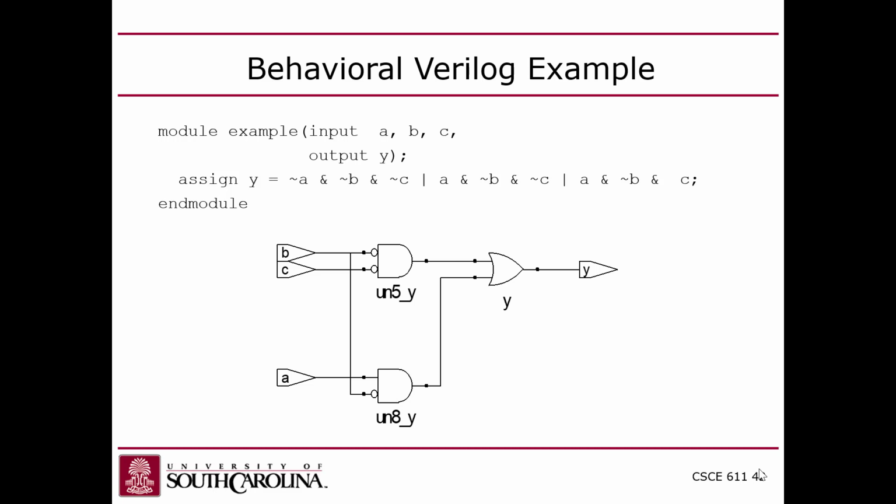Also, these are pins, these are ports, input and output ports for the module. And notice that A is specified as an input and Y is specified as an output, but what about B and C? Why is it vague? Well, it's because B and C are inputs because the most recent specifier was input, right? So it's implied that A, B, and C are all inputs because B and C are unspecified, so they're assumed to be inputs. You can say input before each of these if you want, and that would be another way to make it more easily readable and verbose.